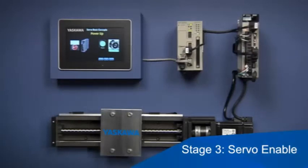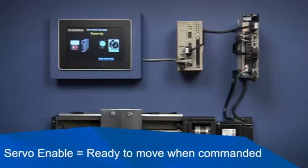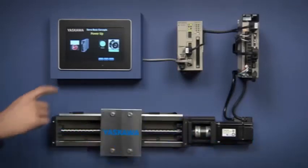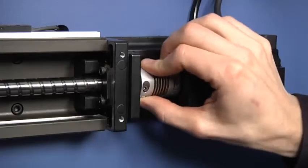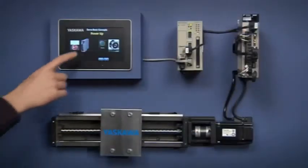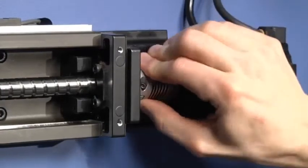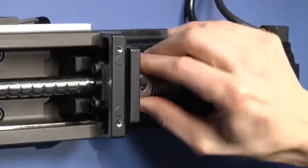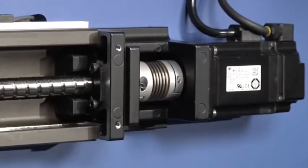This signal to enable the motor comes from the controller. Servo enable doesn't mean the motor is moving. It only means that it's ready to move when commanded. Before the servo is enabled, the shaft will easily move. But if you manually try to turn the shaft while the servo is enabled, it will hold its position. You may hear a hissing sound as the servo works to maintain this position.